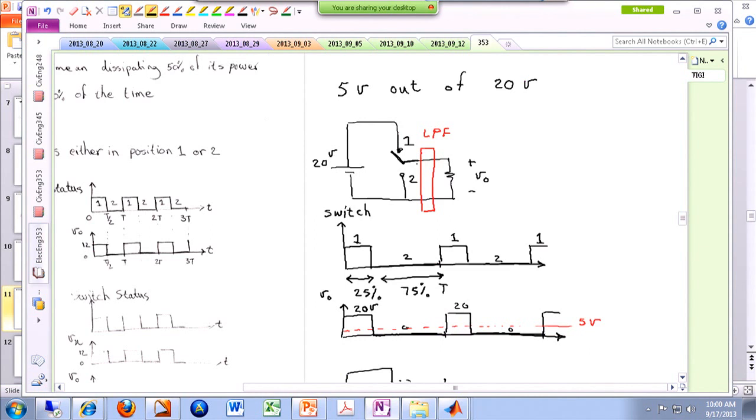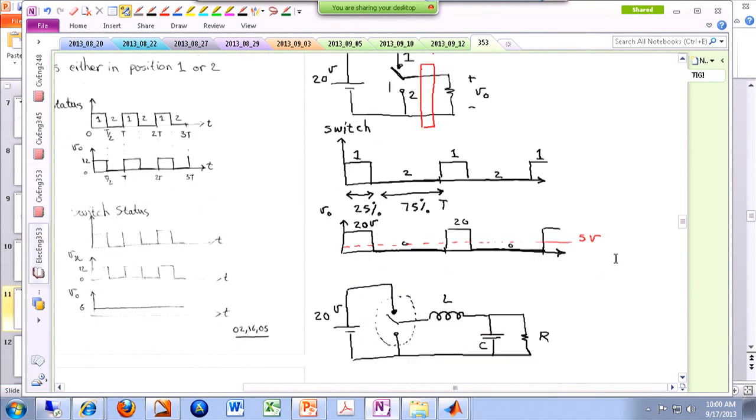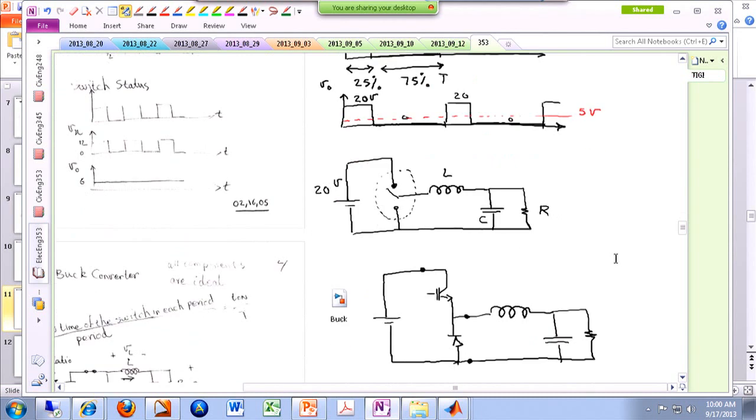and you may argue that some IGBTs have an anti-parallel diode with them, and no problem, this diode over here is never going to get involved. It is as if it doesn't even exist. So that is actually a hint for us. If you want to use a MOSFET, we can actually do so. Instead of this IGBT, you can also use a power MOSFET.